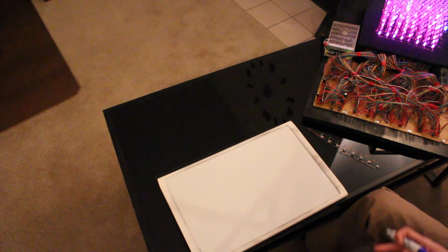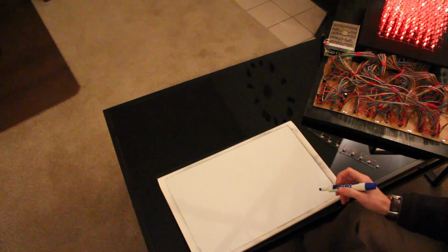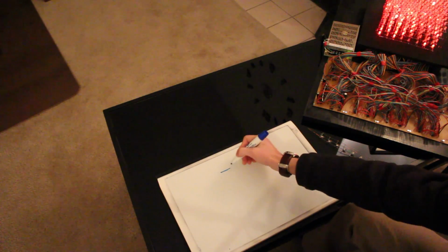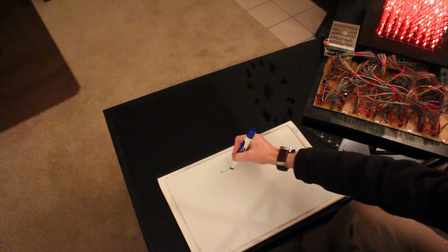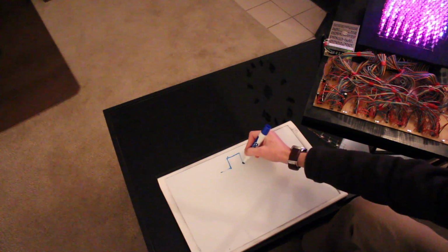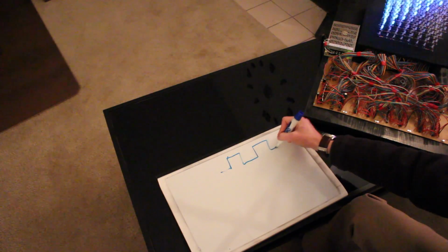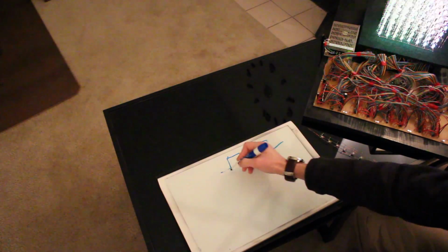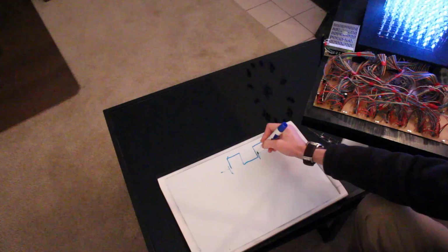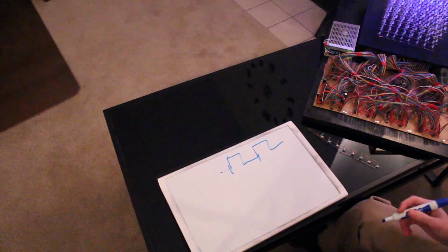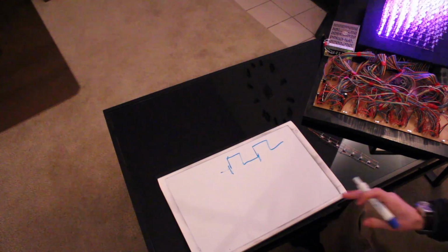I hope all that was clear, but PWM is like this. If you wanted to control something for 50% of the time, you get a 50% square wave, something like that. Your carrier frequency here is fixed at some value. Bit angle modulation is a little different.